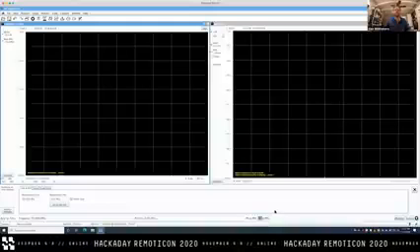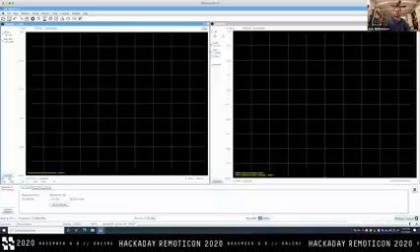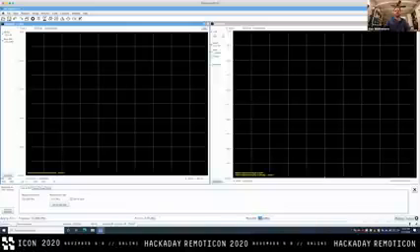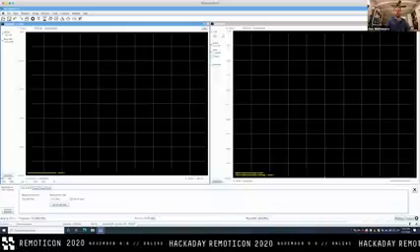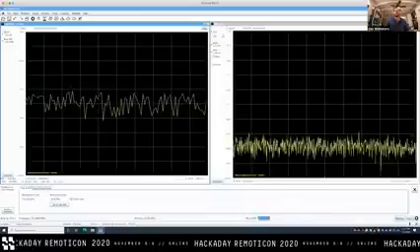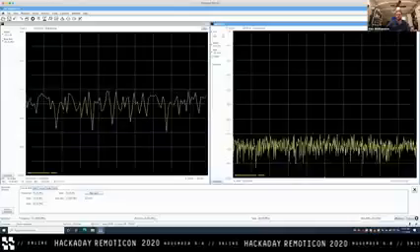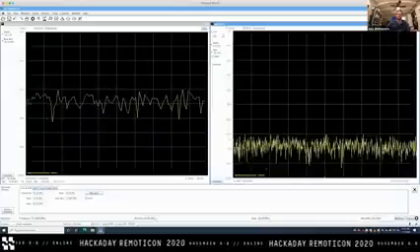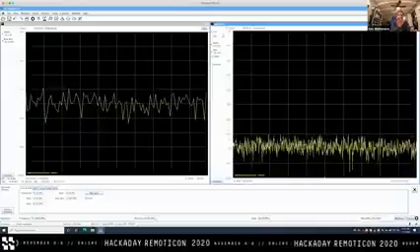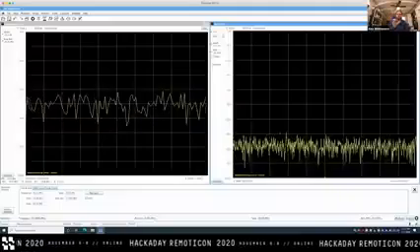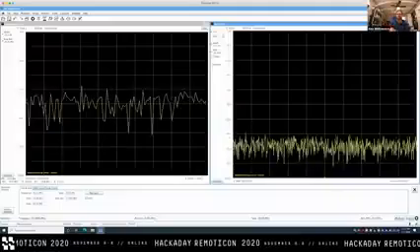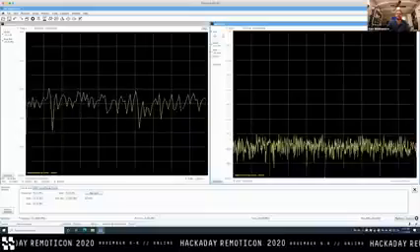So this is one of those aspects. This RSA has a real-time bandwidth of about 40 megahertz, which means if I'm looking at this spectrum view, it looks like it's one continuous spectrum that it's capturing over and over again, but what it's actually doing is capturing the first chunk, then quickly changing tuning frequency, capturing the second chunk, and so on for the width of my bandwidth.